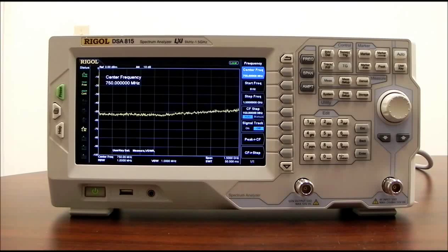Some typical applications are monitoring RF or radio communication channels. How much bandwidth a particular channel may be taking up is a pretty common example. Measuring filters if you're designing radios or you're using filters to help clean up some of your signal levels. You can then characterize the filter with respect to frequency using a spectrum analyzer and a tracking generator, which we'll get into a little bit later.